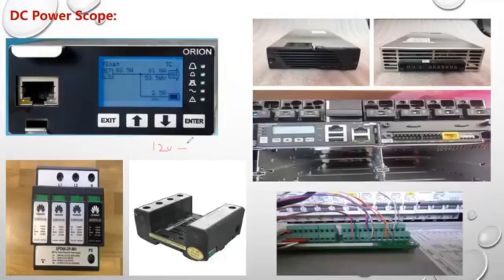Now 12 volts, then I will need 12 volt batteries. I need 4 of them to give me the 48 volt DC. And for 2 volt batteries, I need 24 to give me the 48 volt DC. Okay, 48 volt DC.